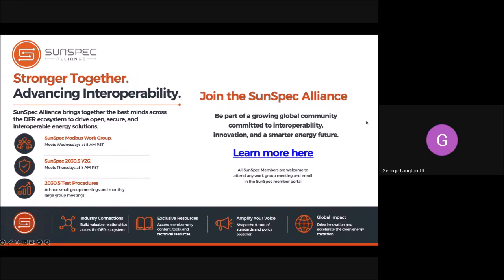Paul, if that helps any, I used to build advanced bidirectional industrial inverters that were grid formers. So I have to tiptoe because I'm now working for UL, but I used to build them, and they don't work the way people think they do. There's always the traditional belief that you form a power on the bus bar and all will follow. That's not the way it works. Inverters are not inherently magnetic. They don't follow Lenz's law. They are control oriented. This is where, for you guys at SunSpec, it's going to be a critical issue. Controls, communications platforms, and data packets are essential.